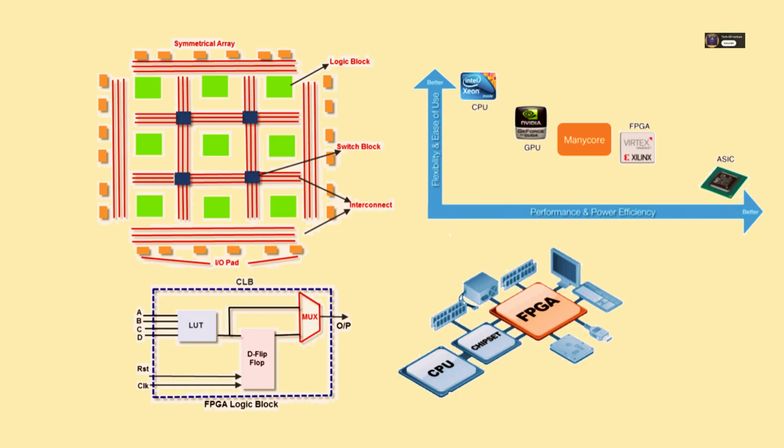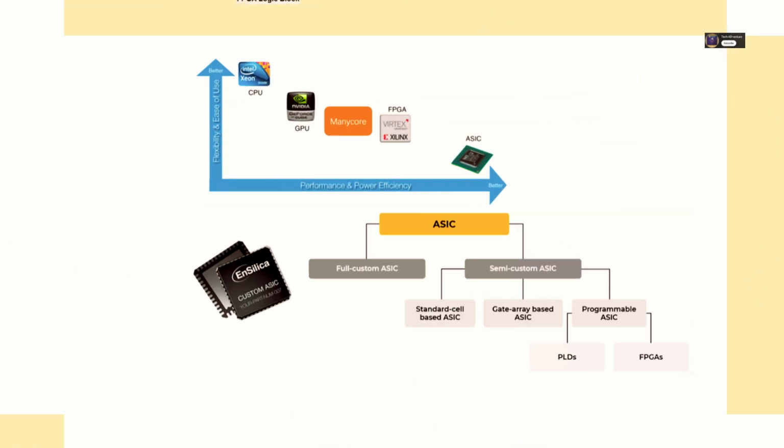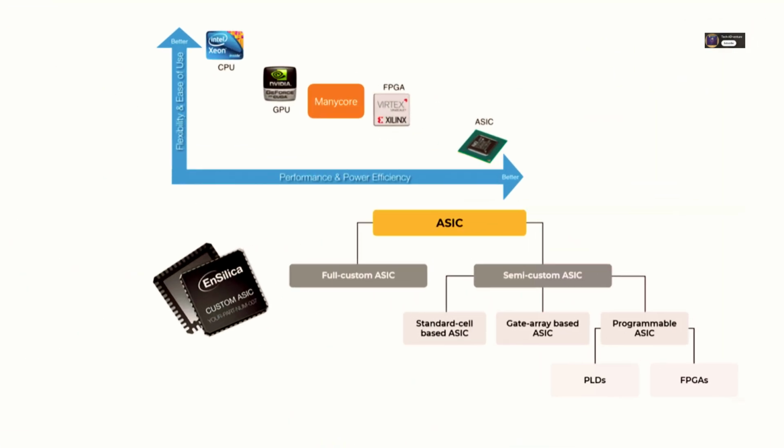You have to use hardware description languages, HDL, like Verilog or VHDL. And if you describe that circuit incorrectly, maybe get the timing wrong, you introduce instability. You have to think parallel hardware processes all running at once, not just step-by-step software. That complexity is a major barrier for many teams. Okay, that makes sense. And then finally, the fourth cornerstone, the ultimate fixed function performer, the ASIC,